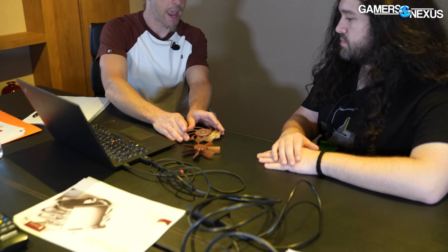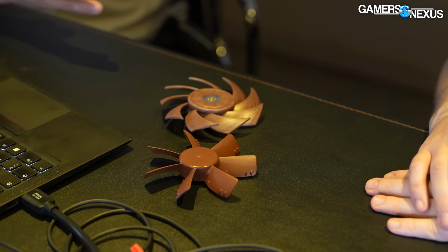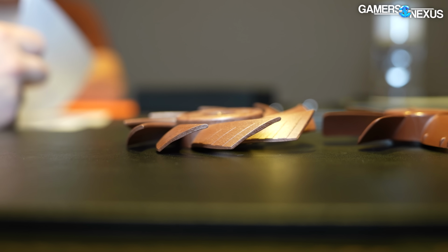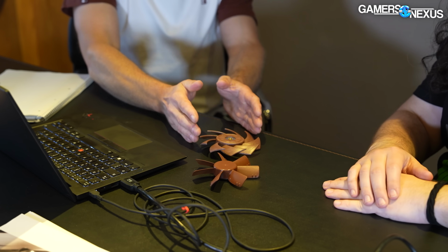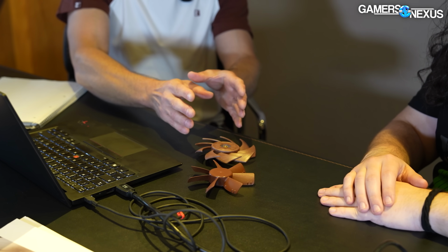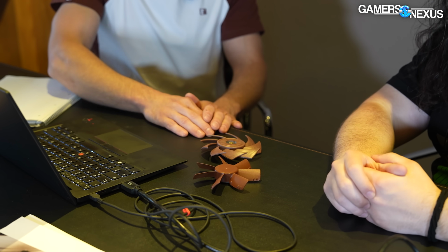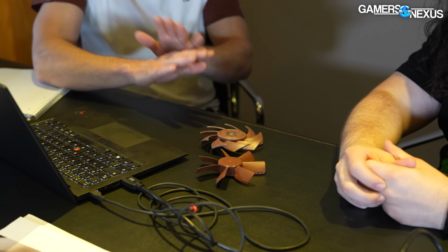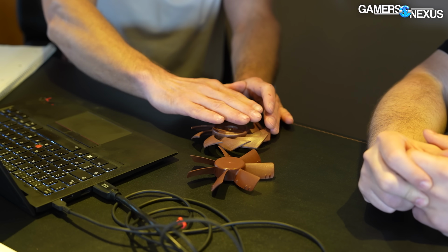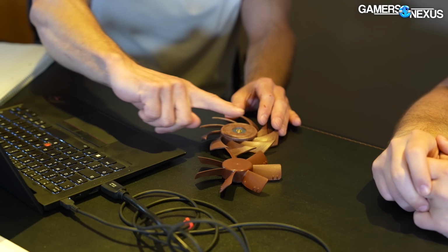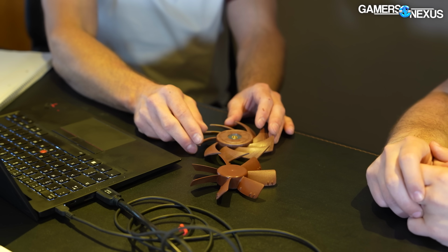Versus angle of attack is defined as the angle between that chord line and the relative flow angle or vectorial flow angle. And this flow angle is defined by two other vectors. The first is the axial flow direction. So you can imagine the fan pushing out air, and we assume for simplicity's sake that this is uniform across the entire diameter of the fan, which is not the case, but it will make things easier to explain if you assume it. So we have air going through like that, and then at the same time we have the fan rotating. So the blade is moving within that plane of rotation.